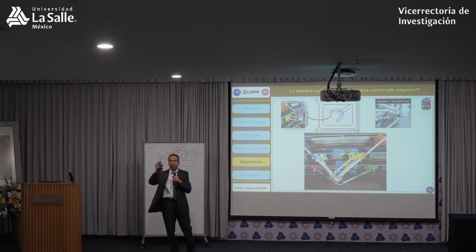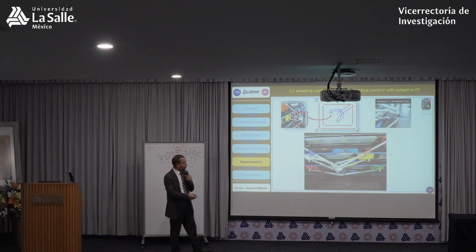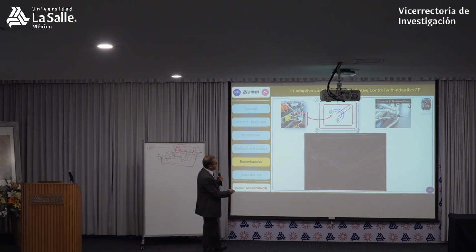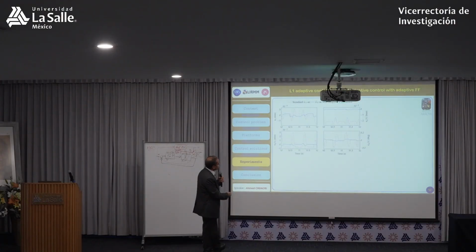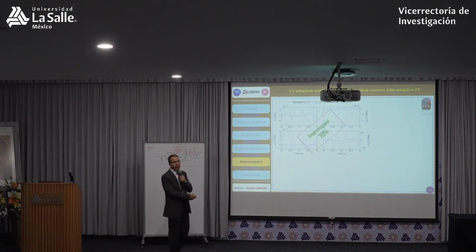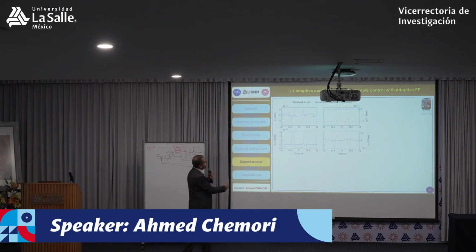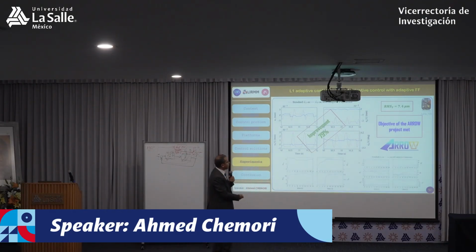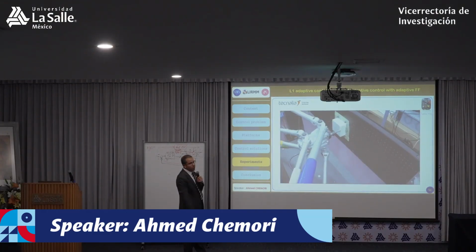And here we are not doing machining, it's just a demonstration of the motion of the degrees of freedom. Here we have 4 degrees of freedom of this moving platform, and this is the reference trajectories. And then the obtained curves here, as you can see, 79% of improvement in terms of tracking error when you extend the L1 adaptive control to feed-forward based on the dynamics. The tracking error root mean square is 7.4 micrometer. You can see the precision of the tracking. And estimated parameters here.